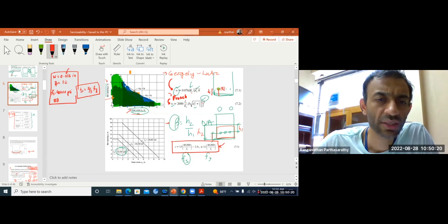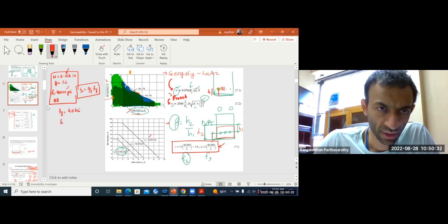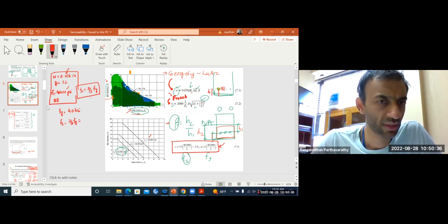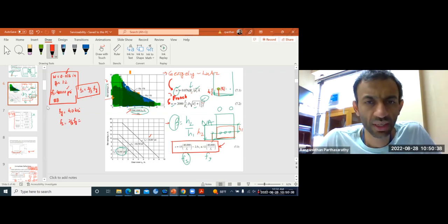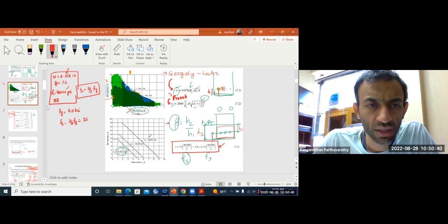Now this is, as I said, for 40,000 psi. Now Fs: if Fs is smaller, like let's say you use Fy is 40 ksi, then your Fs can be taken as 2/3 of Fy, which is 2/3 of 40 ksi, which is 26,667 psi.